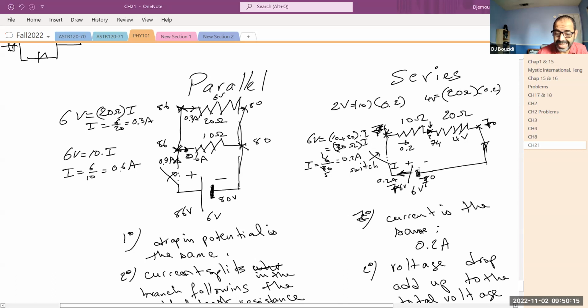However, if you put it in here and any point in here, it's going to read 6 volts because you're going across the battery. The battery is still good. It's still making 6 volts. But whether you're going to drain current from it or not depends on whether the switch is open or not. Okay. The same thing in here. If you read the switch, the value in here, you're going to find 6 volts. But in here, there is no current flowing, so it should be 0. Same thing between this point in here, there is no current flowing, so it should be reading 0.